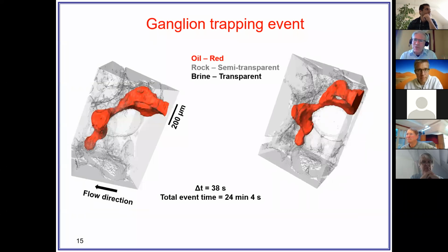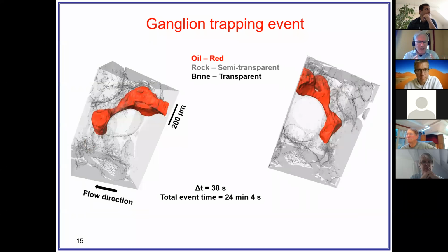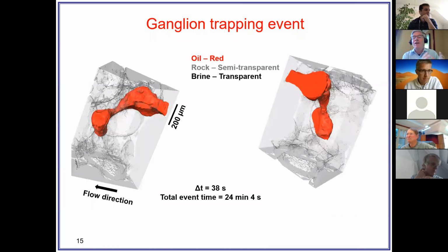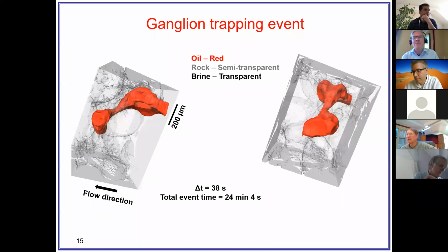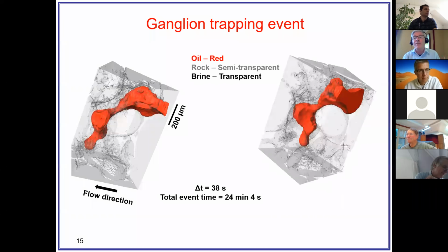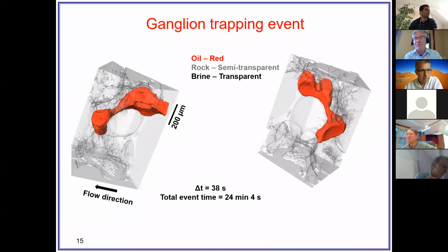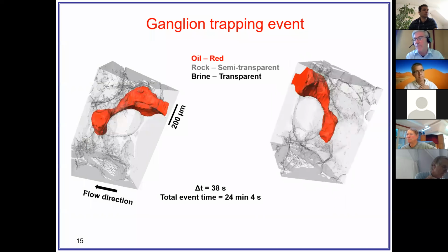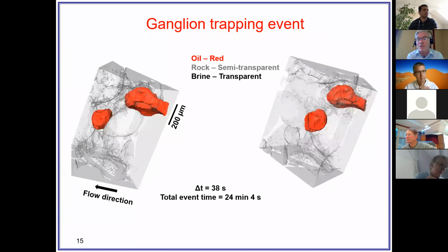And in fact, that's one thing that's really come out clearly from our work: there isn't one contact angle. This idea that there's one number that describes wettability is actually completely misleading. There is always a range of angles. And you see this particularly when you're around neutral wettability. So that's an excellent question, Lynn. That's an important point that I didn't stress in the talk.